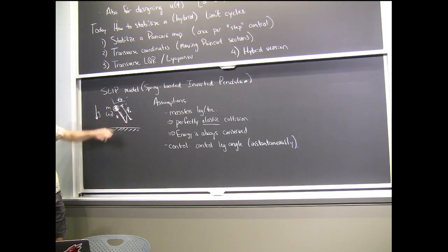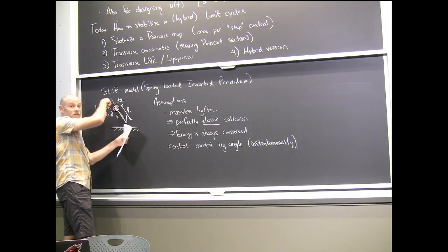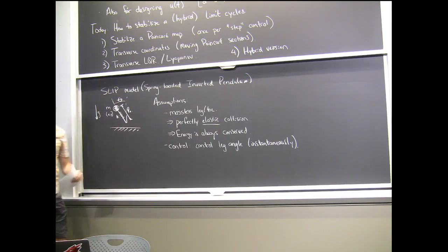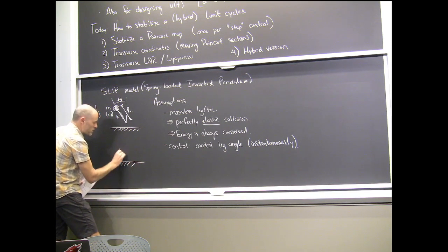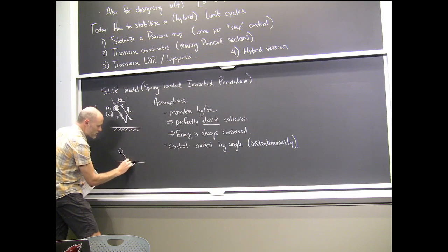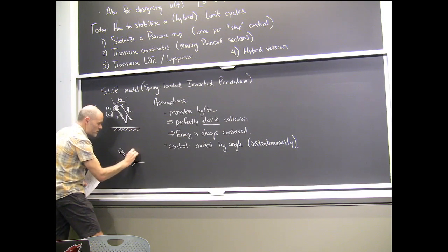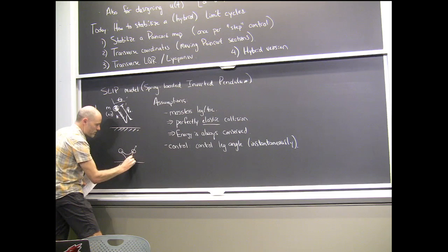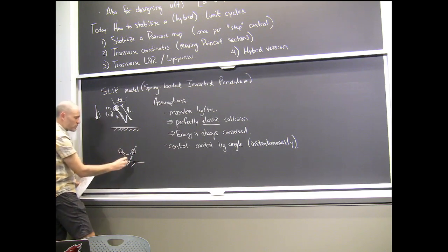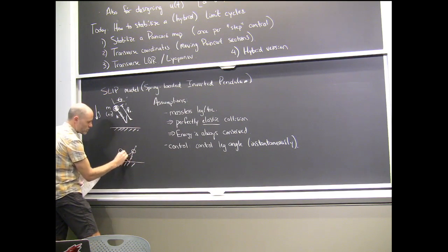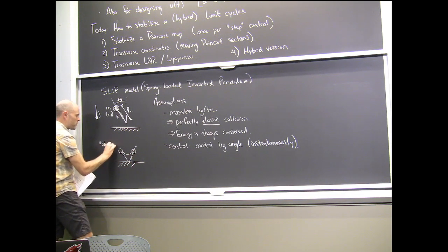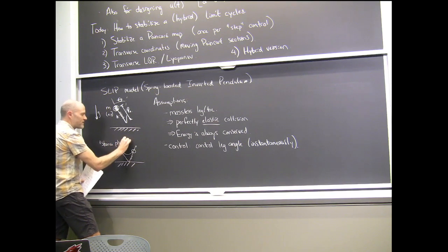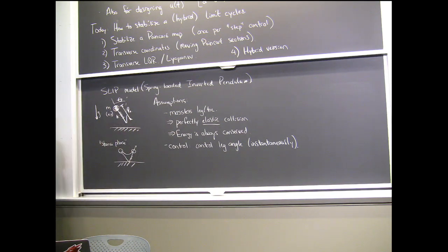But then when it's in contact with the ground, suddenly we have a new model that we have to write, the equations of how the leg interacts with the ground, right? And so the periodic solutions will have trajectories that look like this, where it compresses and leaves and takes off again. We assume that it takes off when it gets back to its rest length, okay? And we have to write the dynamics of the stance phase also. But that's easily done. These choices of making everything simple make it very simple to write the dynamics of